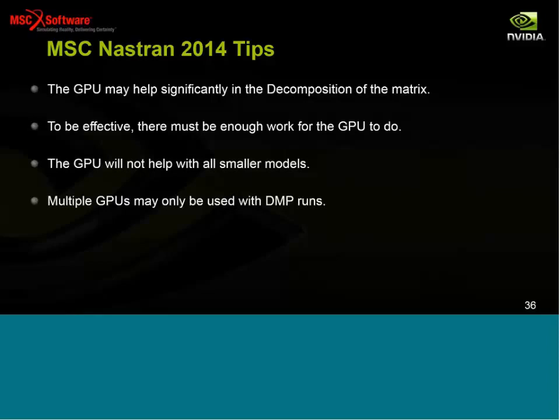Before turning over to Bhaskar, I just want to briefly talk about the future roadmap. We are looking at using the CAE solver that's going to be officially released from NVIDIA in the future. The CAE solver provides new LAPACK options to be performed on the GPU, and this can provide some additional performance improvements when we have dense calculations within MSC Nastran. And we are also redesigning our ACMS solver, and in the future, this redesign is going to allow us to more easily move work to the GPU.